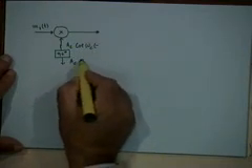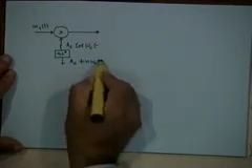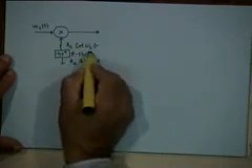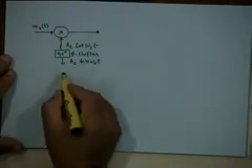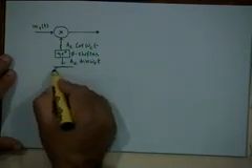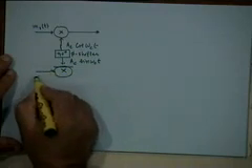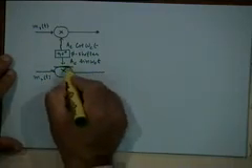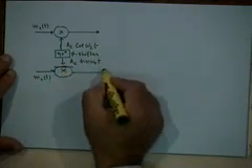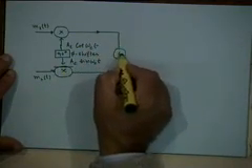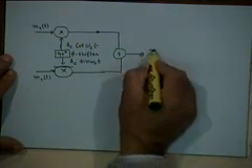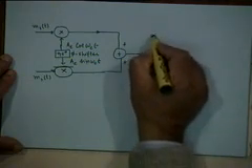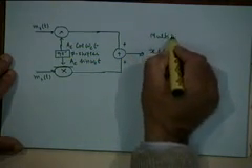Here you will have Ac sine omega ct, through a 90-degree phase shifter. Right? And the second message signal is coming here, m2(t). You multiply this with Ac sine omega ct, and these two are added together and transmitted as the multiplex signal. So this is a multiplex signal.